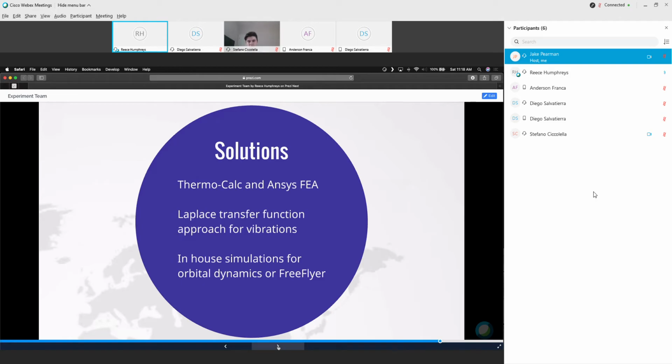And once we have the transfer function, we can predict all of the dampening elements, spring elements, etc. of the satellite. Once we have that, we will have a model of how the satellite will behave under various vibration circumstances. When we have that model, then we can use the payload user guides for whatever launch provider we're using to validate that it will meet all the criteria that's required.